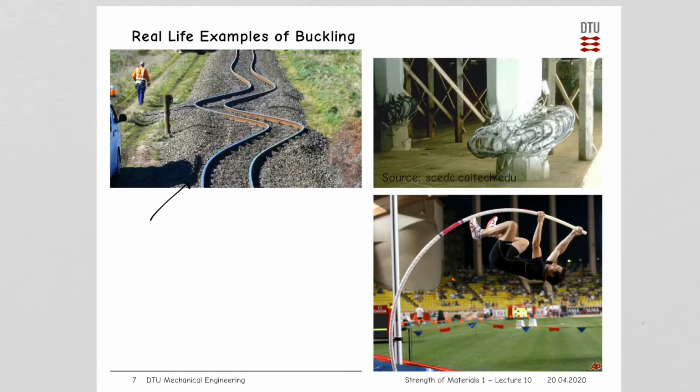look like what you think of as buckling, think of the thermal stresses coming from a thermal expansion when we have a temperature increase of a railway track. So this leads, of course, to actual forces in our railway tracks. And this in turn, as you can see here, if the temperature increases too much and the forces become too large, we will actually see buckling of the railway tracks like this.